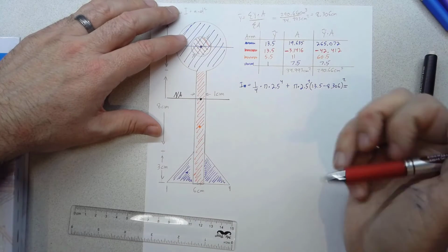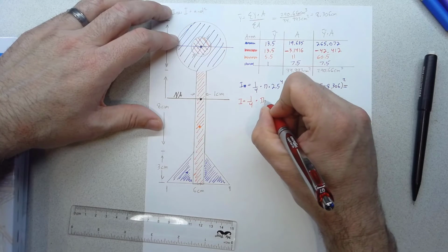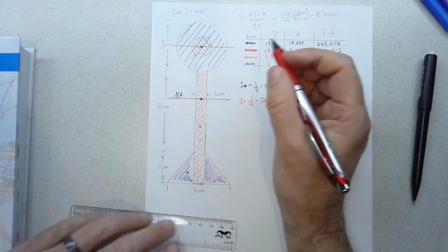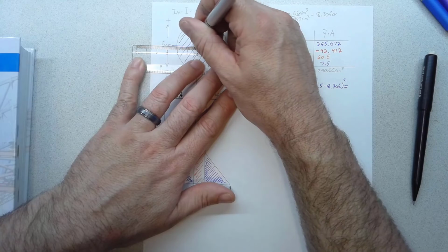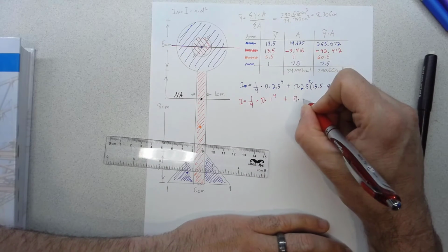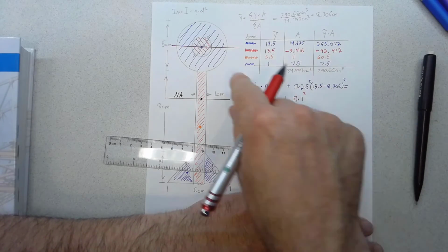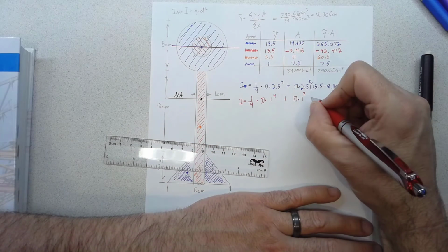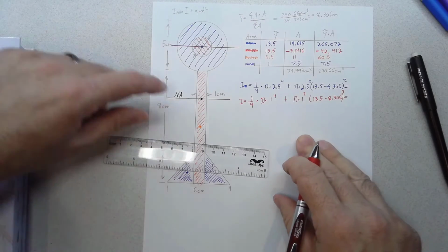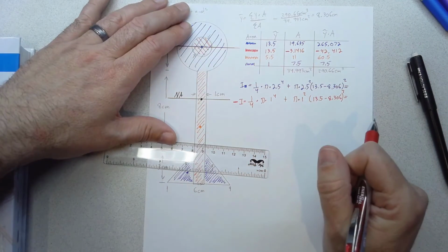Now let's do for the red. Again, it's a circle, so I is equal to 1/4 pi times the radius to the 4th. The radius of the red circle is 1, so that's kind of easy. 1 to the 4th will be 1. But again, that is about its neutral axis, centroidal axis right there. So I need to shift that down to here. So once again, it's area, which is pi times radius, in this case, is 1 squared. That just gets us the A part of the parallel axis theorem. And then times d squared. And the d is going to be the same as it was for blue, right? Because they share a centroid. So 13.5 minus 8.306, that distance squared. That's the I for the red part. And that whole I we can say is going to be negative when we add it together, right? Because we're subtracting that from the total I of the shape.